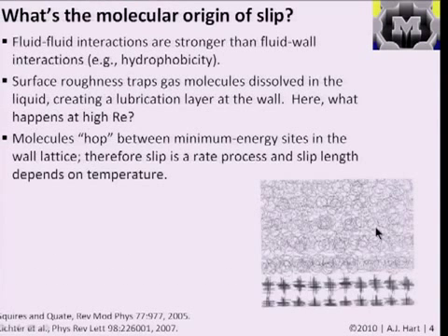And we closed by discussing what the molecular origin of slip is, and we won't get into many particular cases, but basically we just consider that the molecules in the fluid and the molecules in the wall feel each other, and this is determined by the interactions between them, in the same way we thought of van der Waals forces for some simple geometries, and also cases where the roughness of the surface might be important. So if the surface is rough, the effective contact between the fluid and the liquid, or the fluid and the gas, may be different than in the case if it was very smooth.